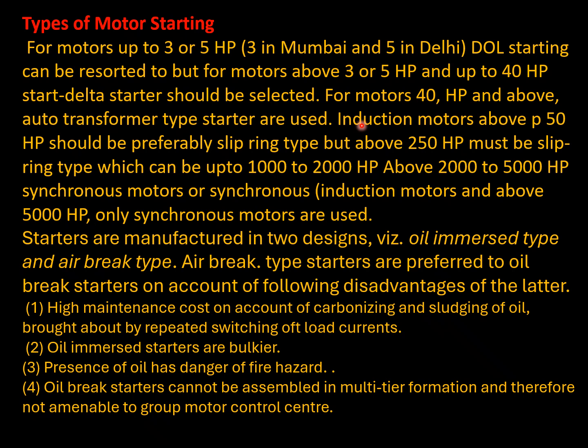Induction motors above 50 HP should preferably be slip ring type, but above 250 HP must be slip ring type, which can be up to 1000 to 2000 HP. Above 2000 to 5000 HP, synchronous motors or synchronous induction motors, and above 5000 only synchronous motors are used.